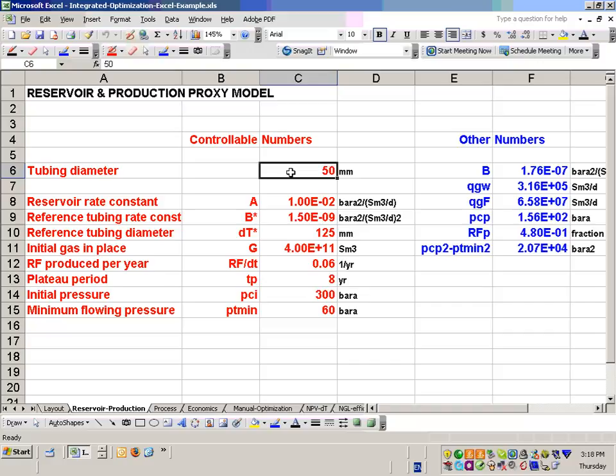Probably the pipeline design for this rate with this kind of tubing pressure that we're producing against. If you go to higher pressure, yeah. You lower the tubing pressure, but then add compression cost, both fuel consumption cost and the actual cost of the compressor itself.